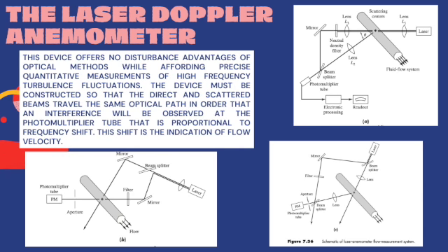To retrieve velocity data, electronics techniques must be employed for signal processing. A spectrum analyzer may be used to determine the velocity in steady laminar flow, as well as mean velocity and turbulent intensity in turbulent flow. The laser beam is split outside the test section, and then two beams can be focused on the exact same point to be studied in the flow field.